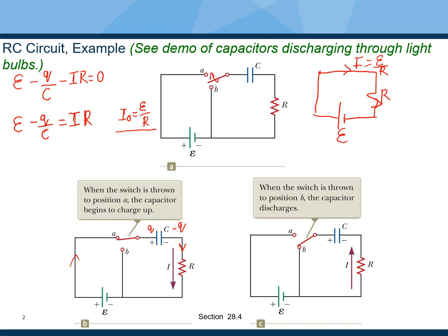Let's also go ahead and understand this from the viewpoint of Kirchhoff's law that we have asserted above. So we see that at t equal to 0, we have a situation where the charge on the capacitor is exactly equal to 0. And as a result, if we put Q equal to 0 in either of the two Kirchhoff's law assertions that we have above, then we see that the current I in the circuit is exactly equal to I0, which is equal to E divided by R.